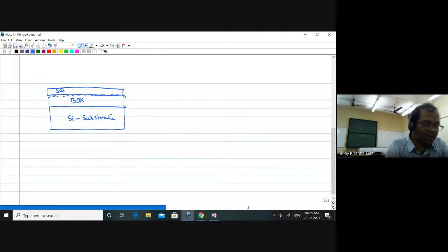You get this substrate from the market, and this SOI itself is a planar waveguide. On the top you can put another oxide, called the top oxide layer, TOX, if you want a symmetric waveguide. But you can also use a selective lithography process so that you create two-dimensional confinement.